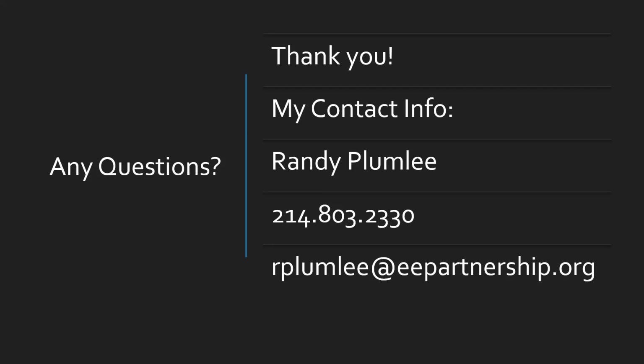When they first started coming out with these rain screens, I told Keene that I was against it. And they said, "What do you mean? How could you be against the rain screens?" I said, "Well, if we can't get the first part, the second part, and the third part installed properly, what makes you think we can add a fourth part such as a rain screen?" And they said, "Good point. We just had someone up in Austin put the rain screen on backwards, and they put the WRB on the inside of the wall, and they put the rain screen on the outside of the wall that just got completely filled with plaster. It all had to come down and be redone." So I think something should be done with that, but it would be so difficult at this point.